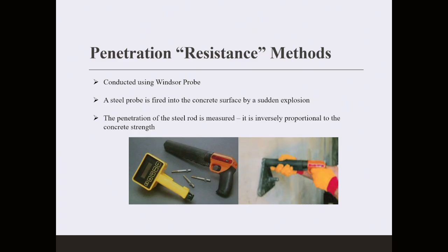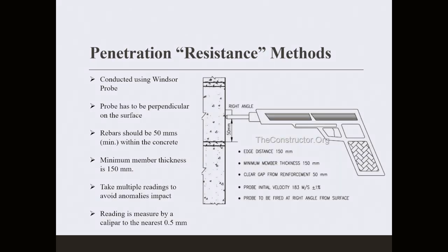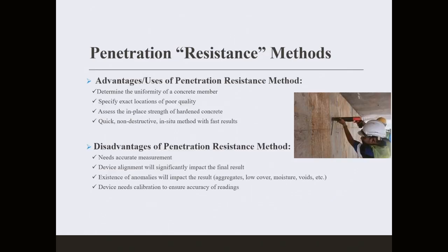Oh, you use the Schmidt hammer. Okay, I mean, it's not very far off. The penetration or resistance method, using the Windsor probe, basically depends on how much resistance there is to penetrating a given surface. The Schmidt hammer, or rebound hammer, measures how fast and how big or how strong the rebound is going to be.